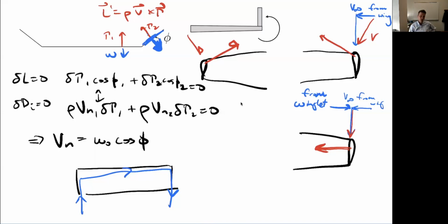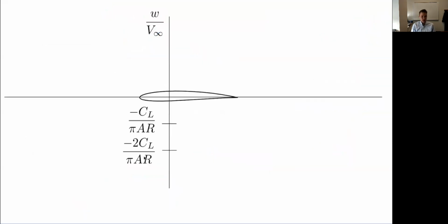Because the wing is really what's doing much more of the work, or really all the work in terms of generating the lift. Any lift the winglet generates, especially for 90 degrees, is not helpful, right? So sideways force is really used here to kind of alleviate some loading on the winglet or the wing. All right, one more thing, just to kind of close a loose end here.